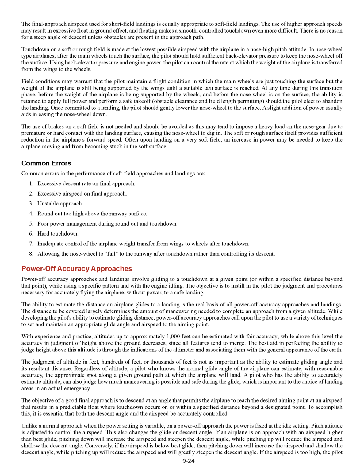Regardless of altitude, a pilot who knows the normal glide angle of the airplane can estimate, with reasonable accuracy, the approximate spot along a given ground path at which the airplane will land. A pilot who has the ability to accurately estimate altitude can also judge how much maneuvering is possible and safe during the glide, which is important to the choice of landing areas in an actual emergency.